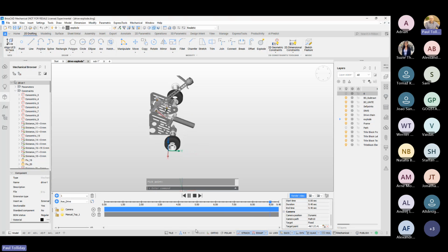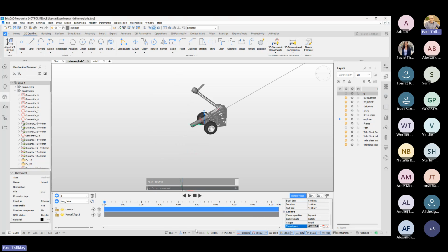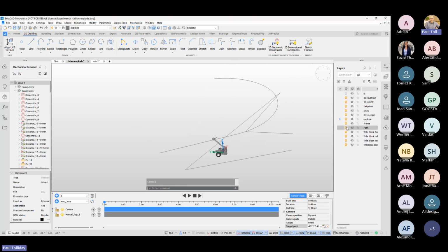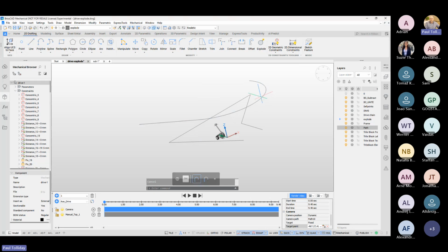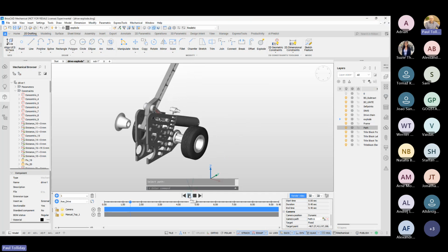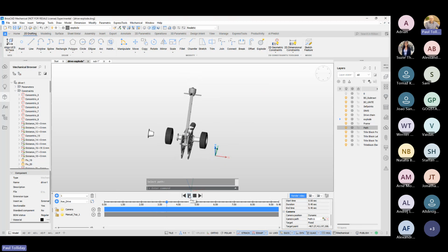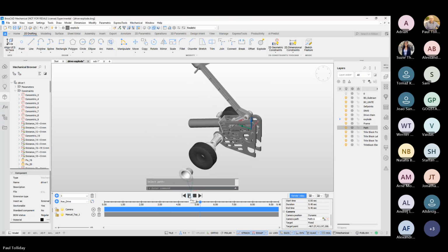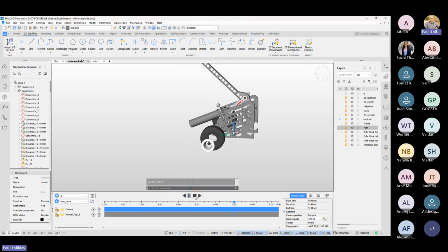And again, you can have as many angles as you want, whatever your artistic preferences are, you can change that and update it. Another thing you can use is 3D polylines. So I'm going to just delete this line here just so you can see it a little bit easier. So this goes in X, Y, and Z axes. And again, we can use this as a dynamic path. I'm just going to select that path like so. And now when we press the play button, we can see we've got multiple views, multiple angles, moving the camera around wherever we want to place that. So you can see, very easy to work with.